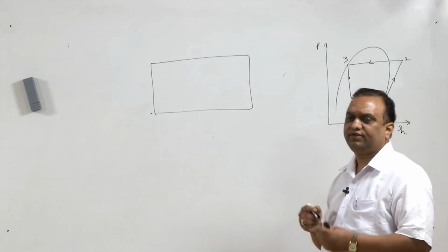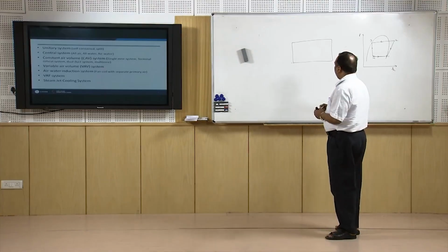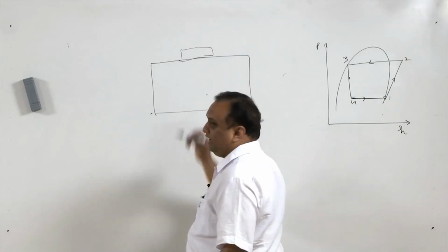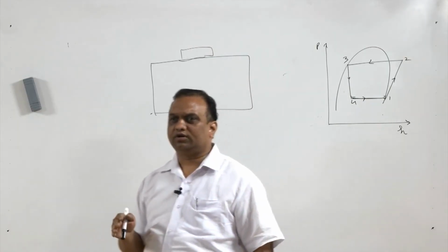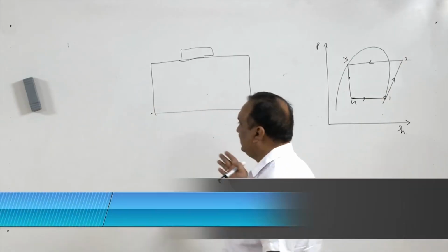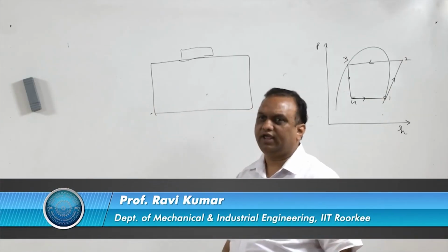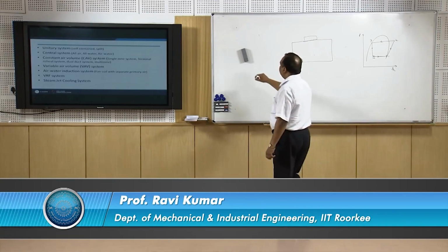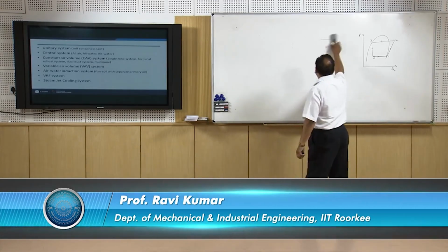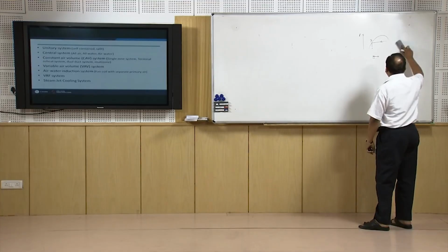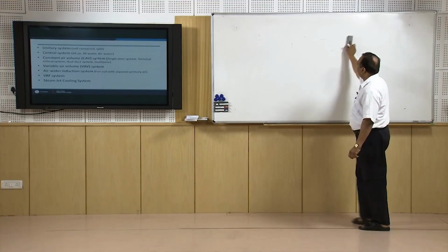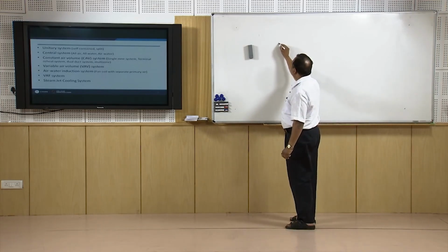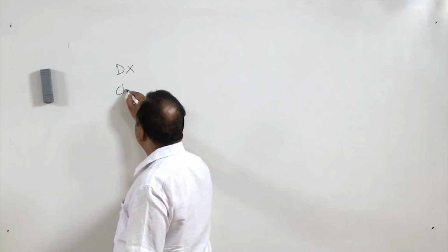There is no secondary refrigerant like chilled water or brine, and this unit is placed at the rooftop, and air is supplied to a room or a set of rooms through ducts. This type of unit is known as a package type of unit. Now a central AC system has a compressor house, mainly in the basement of the building. There are two types of systems: direct expansion type and chilled water type.